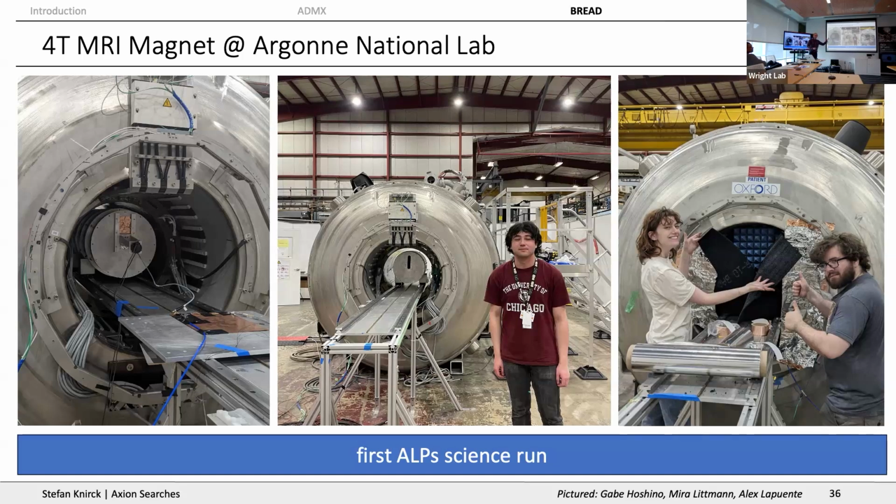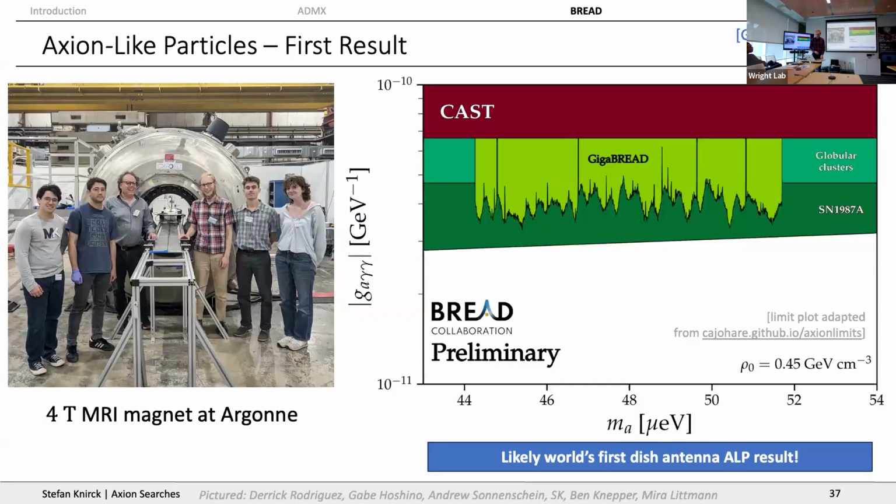You see, now we don't have an electromagnetically shielded room. So we had to do a lot of work to have a rejection data taking chain and a lot of absorbers around the setup to make sure that we don't get all these Wi-Fi signals into our chain, which in the end worked quite well, but was some effort. And now we have the first result. We are just about finishing writing up the paper on it. So this is the result which we got.